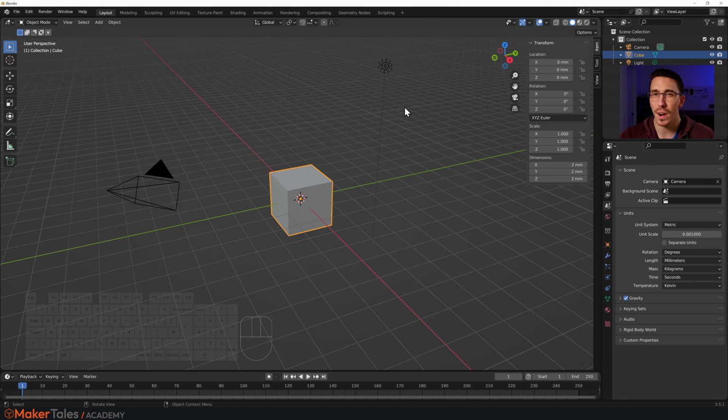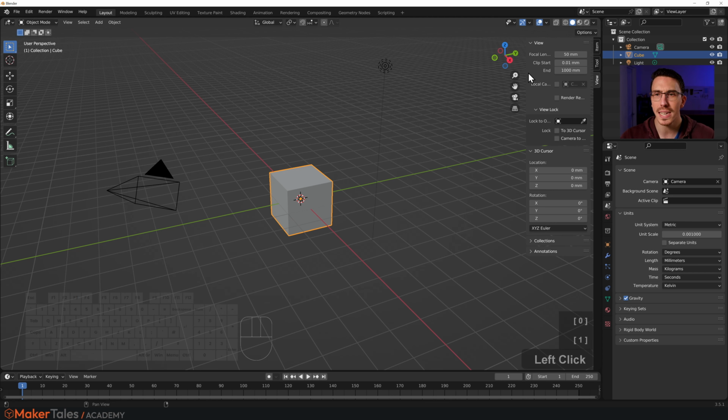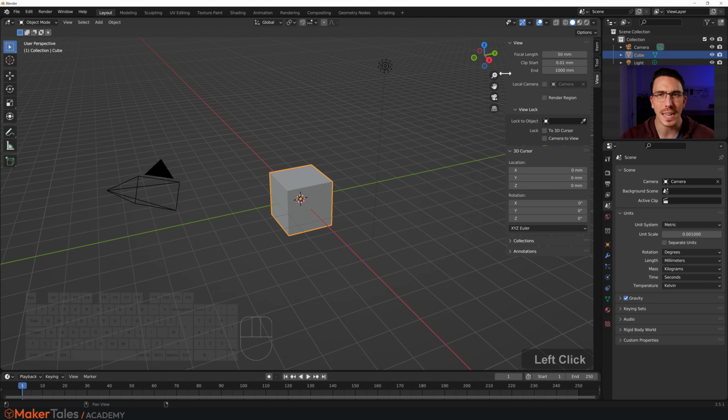Brilliant. Now there is one other thing that we need to change now that we've changed the scale so much, which is our viewport rendering. Now what exactly is the viewport and why do we need to render that? Well, this space here, that is the 3D viewport, the 3D space that we're viewing things in. And this might be a new concept to you, but in the 3D space, we don't want to render all of it all the time because it's infinite. So we have a viewport plane, the clipping plane, there where we see things in. And that's what the clip start is, and that's what the clip end is.